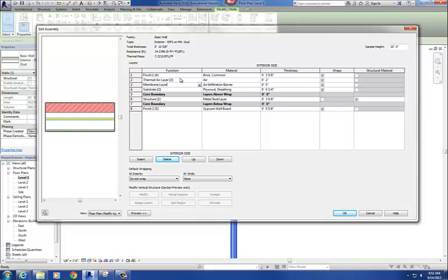All right, and then thermal air layer is going to be either insulation mostly. Like sometimes you'll put rigid insulation on the outside of a wall or something like that, or air. Which in the case where you're using masonry, you always have an air layer behind the masonry. So that's basically what that is. So it's either going to be thermal or air.